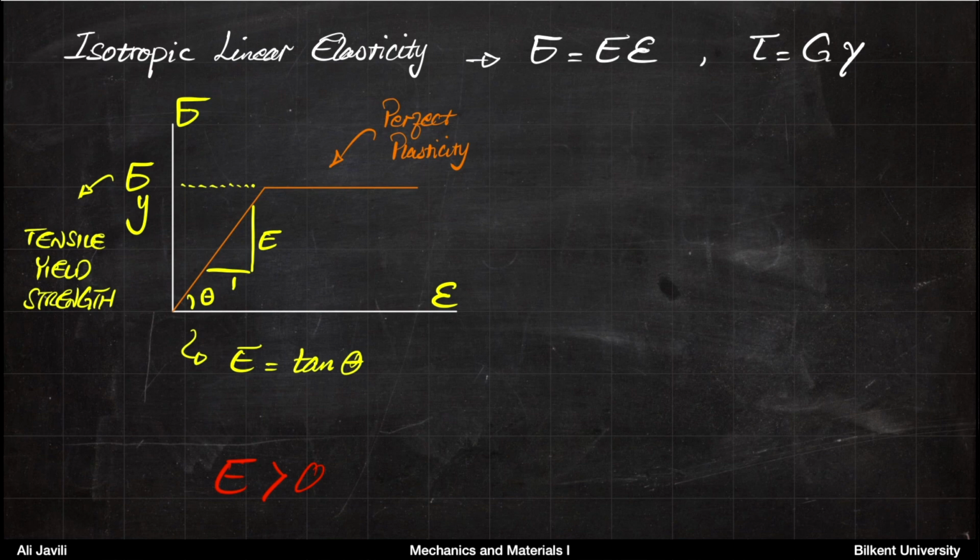So basically, we assume that we have this linear region for which, again, the elastic modulus is essentially the tangent of that angle that you get. Or if you assume this length is 1, this would be E. And then after you reach this, let's say, maximum strain for elastic range, you come to the so-called inelastic range. And for inelasticity, we assume that the material is perfectly plastic. It means it only goes straight. And E is larger than 0.